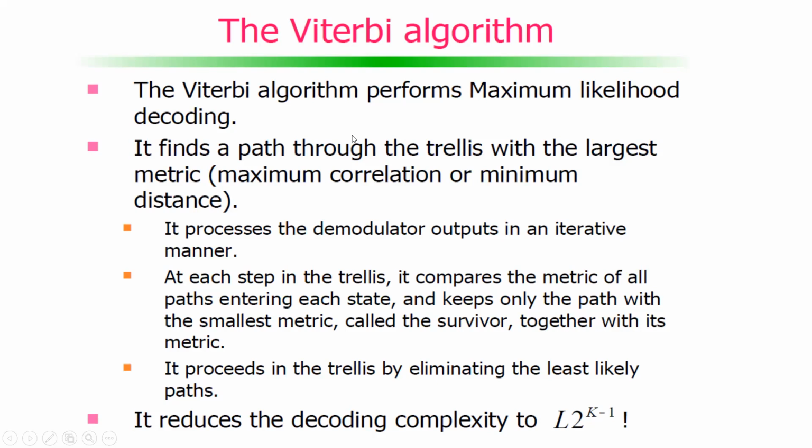Based on this algorithm, he reduced the decoding complexity to L times 2 to the power k minus 1. Let's not go into this figure. The important point is that the Viterbi algorithm reduces the computational complexity to a great extent.